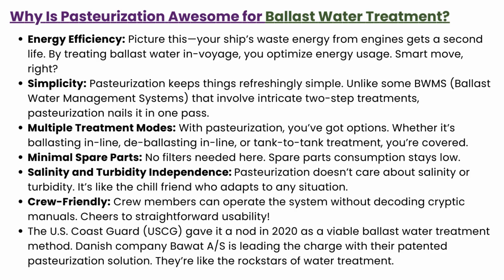Simplicity. Pasteurization keeps things refreshingly simple. Multiple treatment modes. With pasteurization, you have the option of ballasting inline, deballasting inline or tank to tank treatment. You can do it anywhere. Minimal spare parts. Some technologies require too many spare parts, some technologies require minimum spare parts. Salinity and turbidity independence. Pasteurization doesn't care about the salinity, how much salt is there. You can have from 1000 to 1025 or 1028, that is not a problem. It is like a chill friend who adapts to any situation.